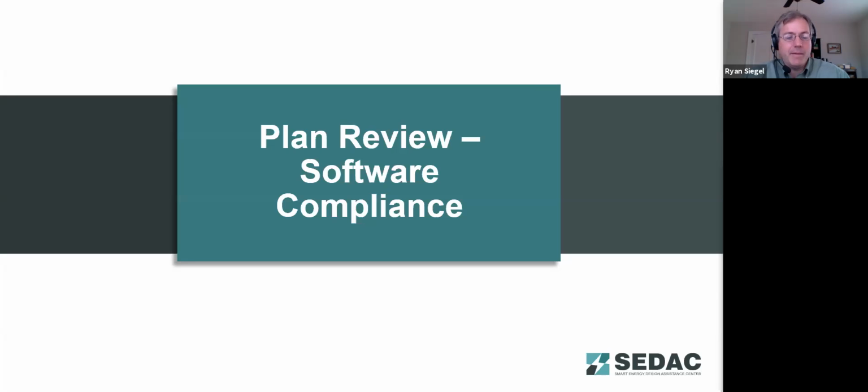However, you would need to pay particular attention anywhere that you have that ICF meeting any other material, making sure that you're detailing what the seal is to maintain that air barrier throughout. So yeah, the ICF area typically already is its own air barrier.